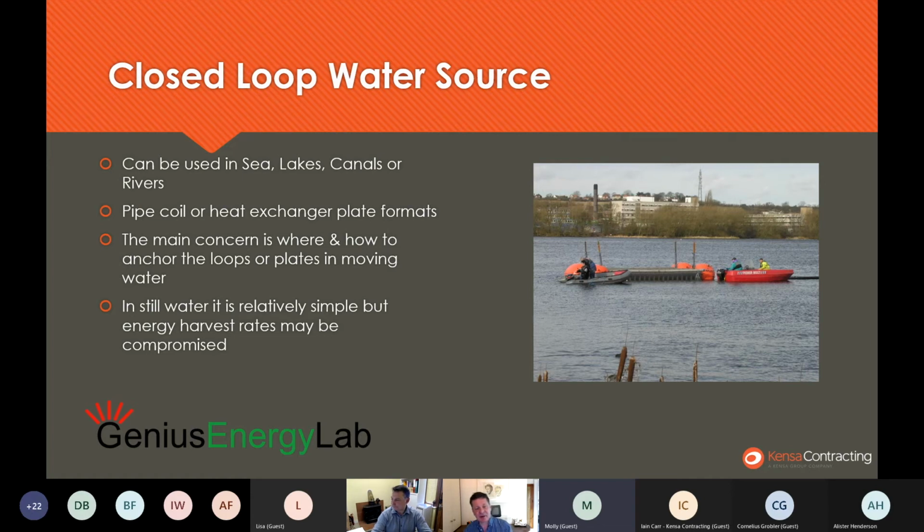So other options for us are surface water. So we can use any body of surface water to exchange energy with. And the beauty of this is that if the body of water's there, a large part of your source is already constructed. Or if you need a body of water for another purpose, I just designed last year a couple of huge agricultural systems where they were putting in water retention ponds for irrigation. So we can utilise that to heat the greenhouses as well.